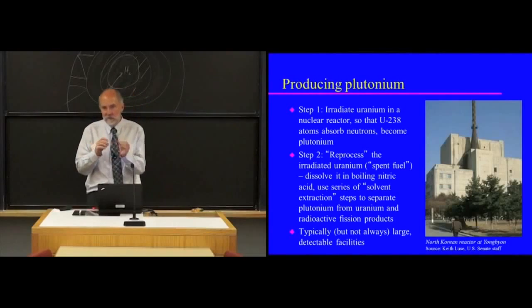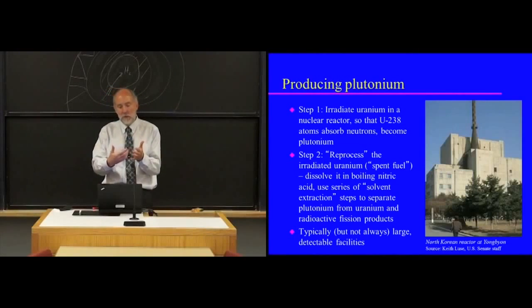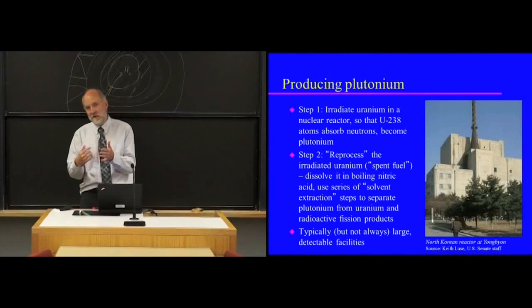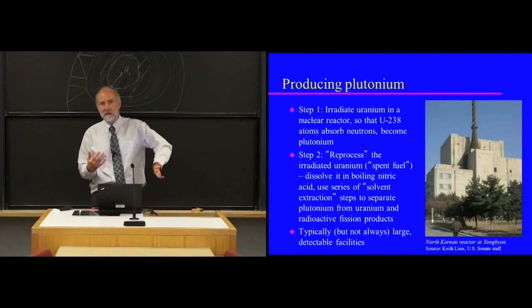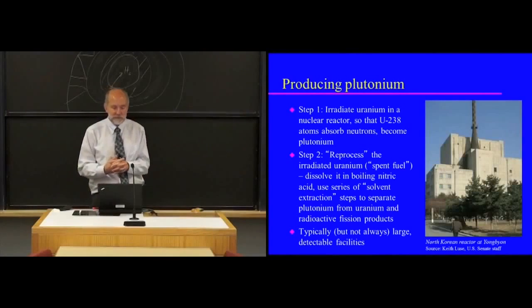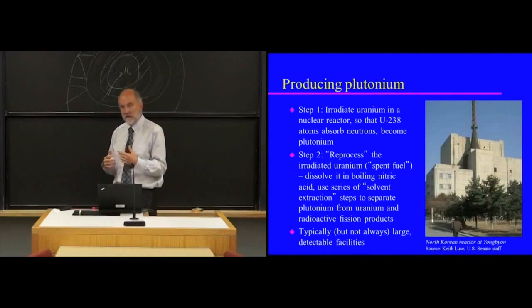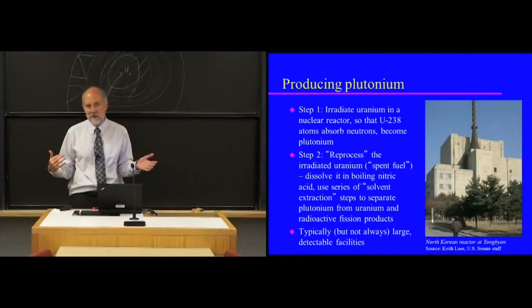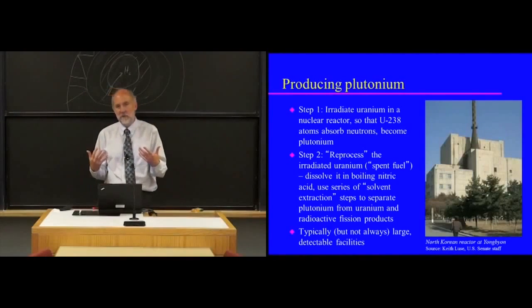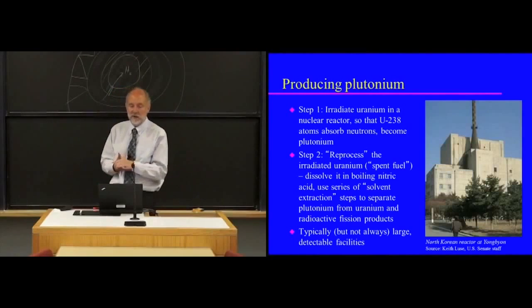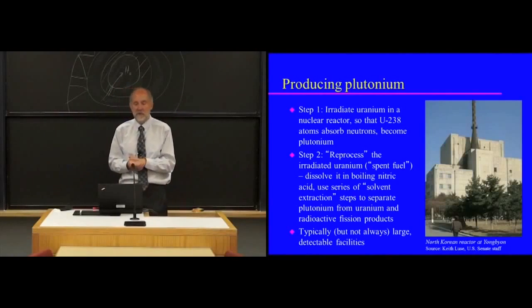If you do certain chemical steps, you can pull the plutonium into the tributyl phosphate, into the solvent, and leave the rest in the acid. Typically, at the same time, you separate the uranium from the fission products as well. So as I mentioned before, you have really three piles: a pile of plutonium, a pile of uranium, and a pile of fission products resulting from the reprocessing.